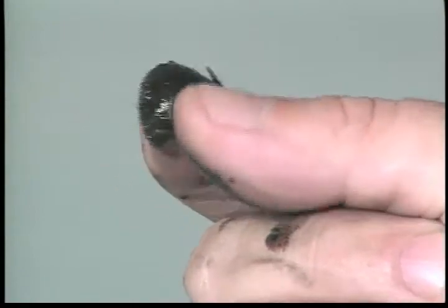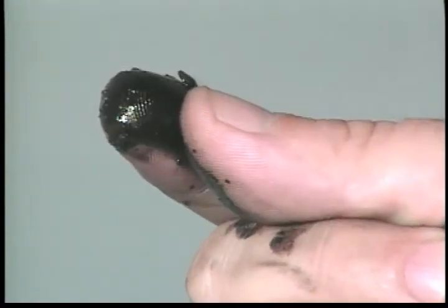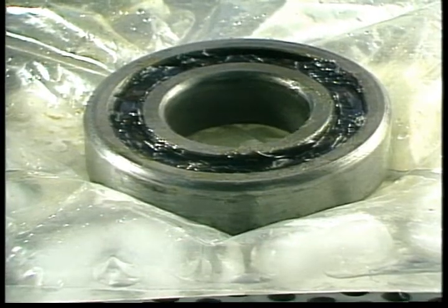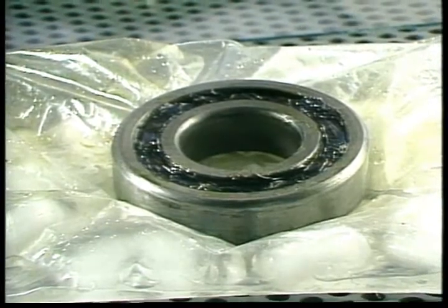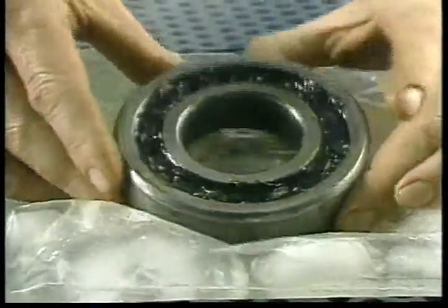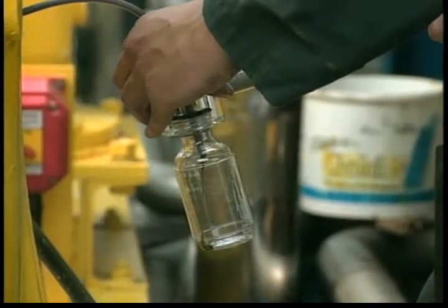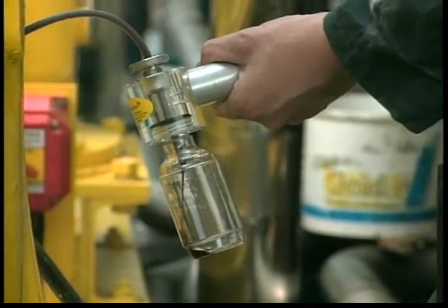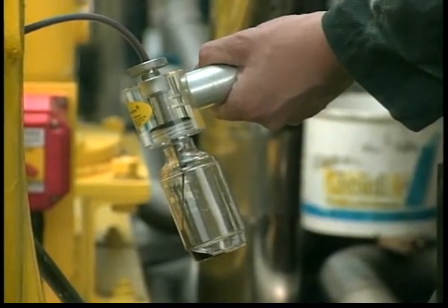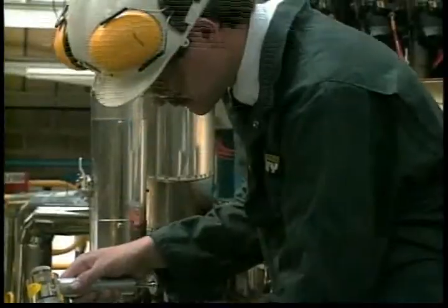Look for any particles you can see. Very small particles will make the grease feel rough or gritty. Grease that is burned or carbonized means the bearing has been running very hot for some time. Any of these conditions may indicate the bearing has been damaged. Checking an oil lubricant follows much of the same pattern as for grease, but checks should be made more frequently. Systems that use oil generally operate at higher temperatures, and the useful life of the oil will generally be less.